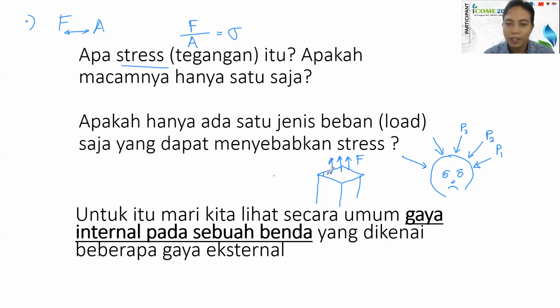So here we can say that stress is the intensity of load, right? Intensity of load, which measures the severity of the problems. So here, how do we modify the stress? If the problem is the same, if the load is the same, we can increase the surface to decrease the stress, right?